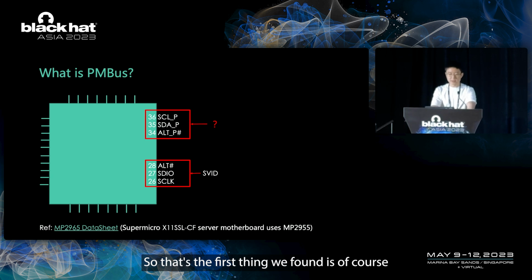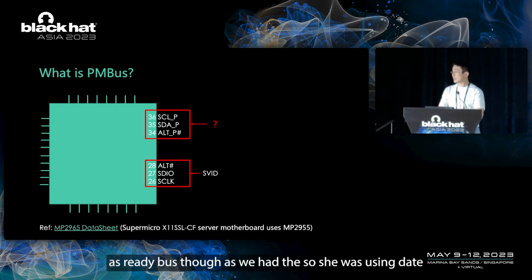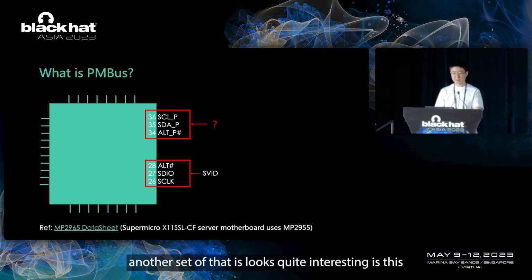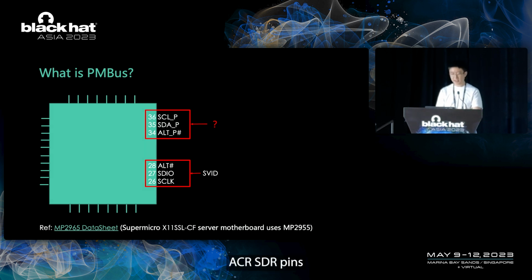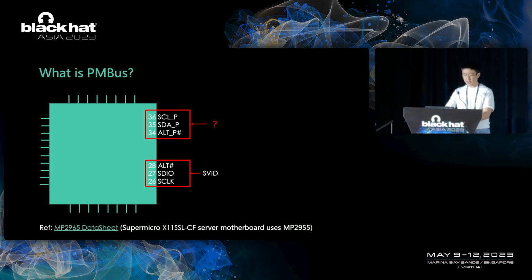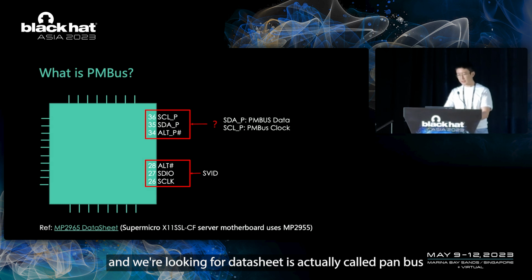So the first thing we found is, of course, the SVID pins, which were used in VoltPillager. And there is another set of pins that looks quite interesting: the SCL and SDA pins. At first look, it looks like an I2C interface. And we looked into the datasheet.